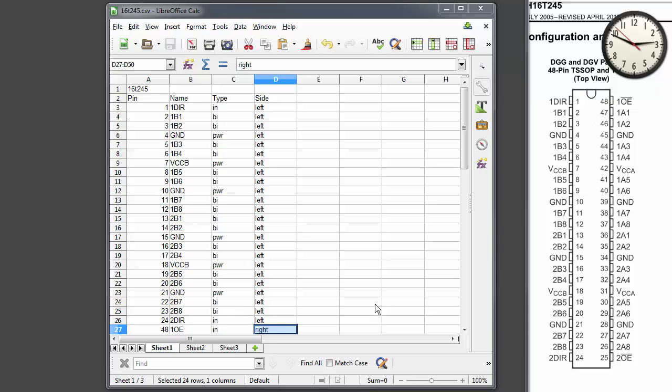You want to have different units within the symbol itself that correspond to different functions that may be in that chip. For example, with an FPGA, there are banks of inputs and outputs that are all connected to a dedicated power supply for each bank, and so you would want to have a unit inside the symbol for each bank. And we can do that with KiPart as well.